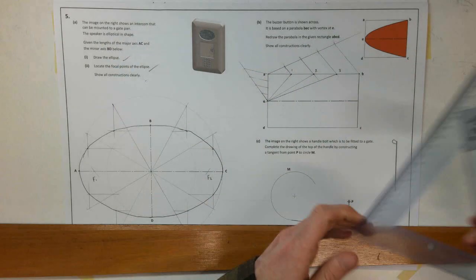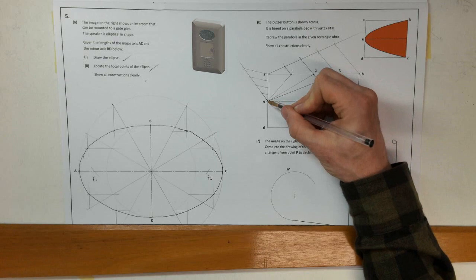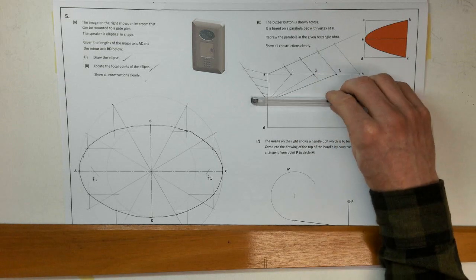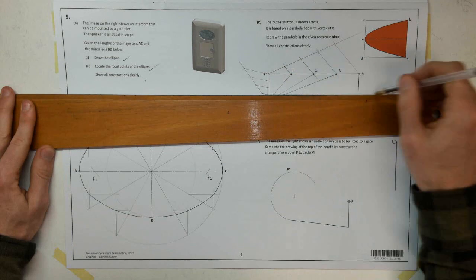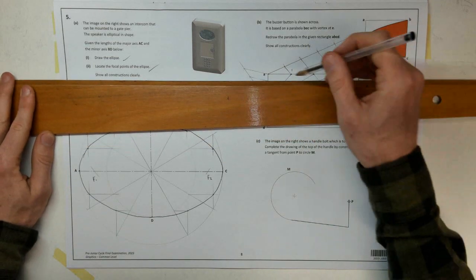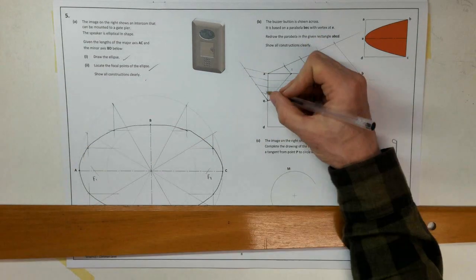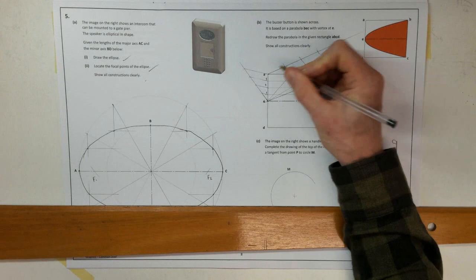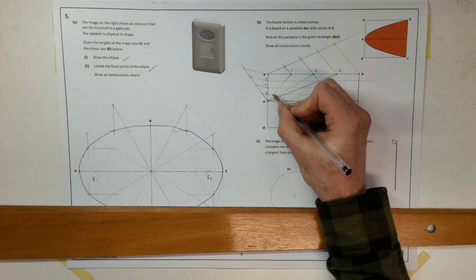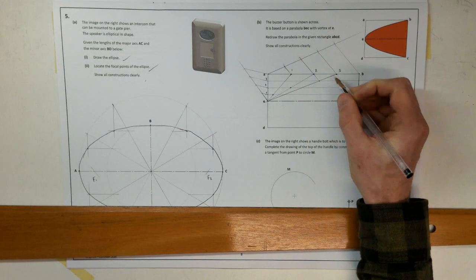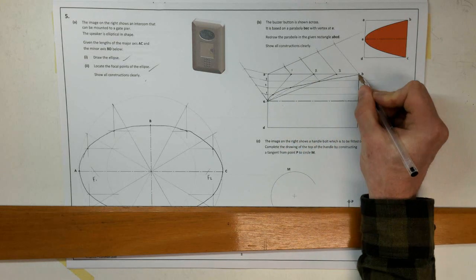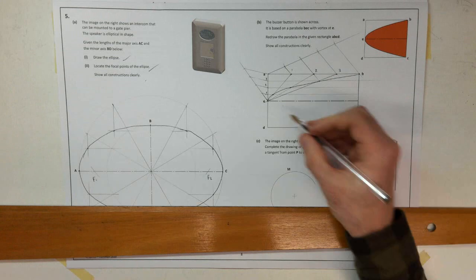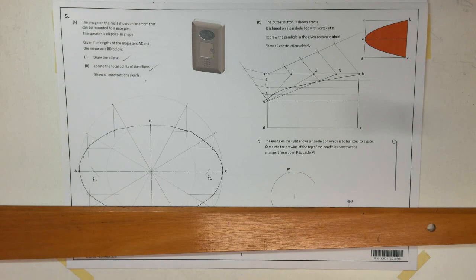So the side that contains the vertex is going to go parallel to the axis line. So dropping a line down, down, and down. This is point 1, point 2, point 3. So 1 and 1 match up, 2 and 2, 3 and 3. And we can freehand curve that, looking at the point we're traveling to, back like that. That's half of our parabola.